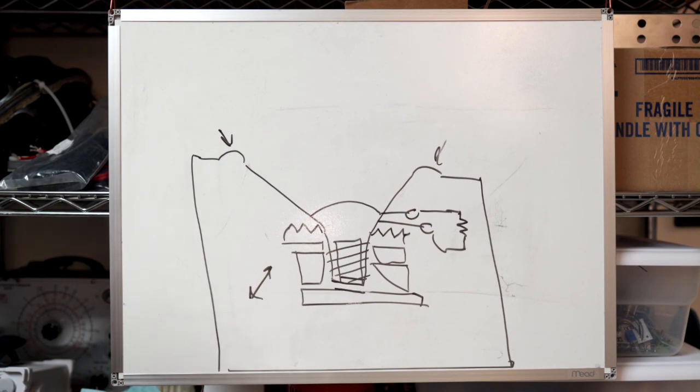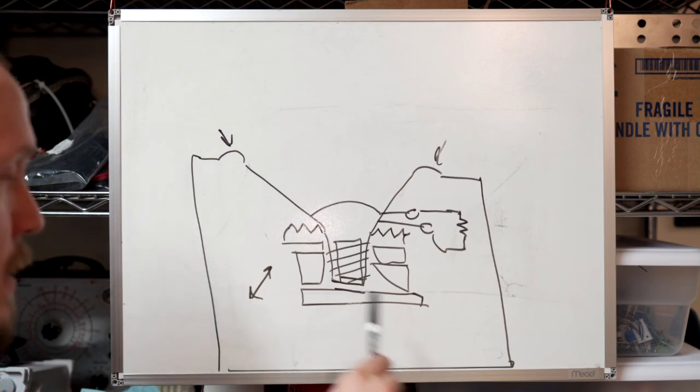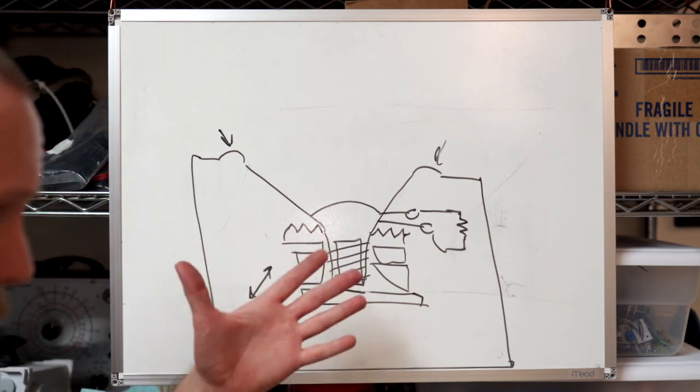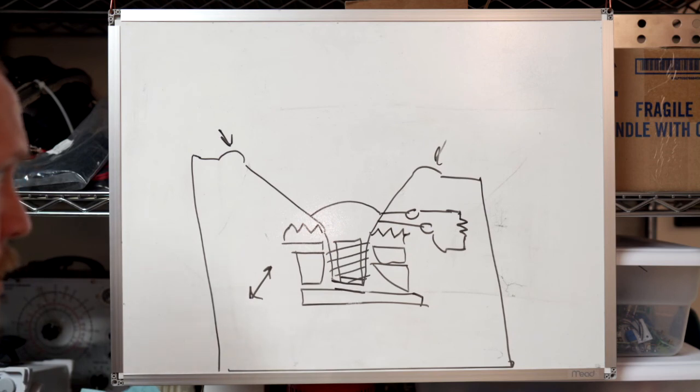So we're not talking about having no dampening. Obviously, it's still going to be low-ish. We're talking about 5 ohms versus 1 ohm or something like that. But it can change the distortion also of the speakers. Obviously, getting tones out of your woofer that are not the tone that you put in is distortion. But I think that's basically what we're talking about. Tube amps, we're talking about a little bit of distortion that is pleasant.